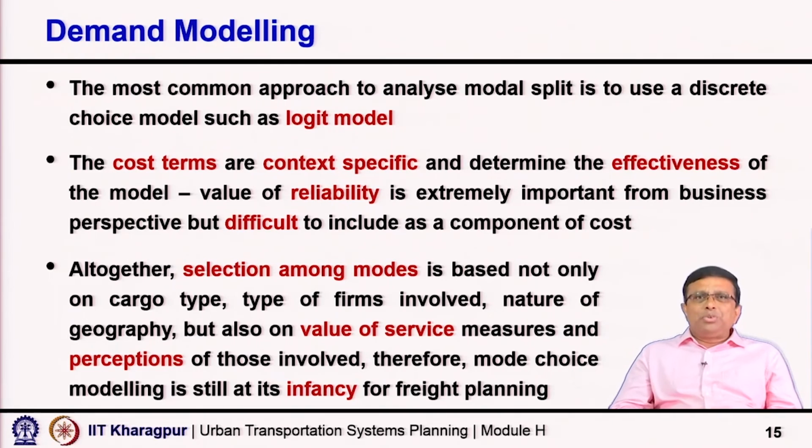The most common approach to analyze modal split is to use a discrete choice model such as the logit model. As I said, the future is discrete choice or disaggregate models, and a variety of logit models are used. So, for passenger transport and goods transport, in both cases the logit model or behavioral based models are going to be used extensively.